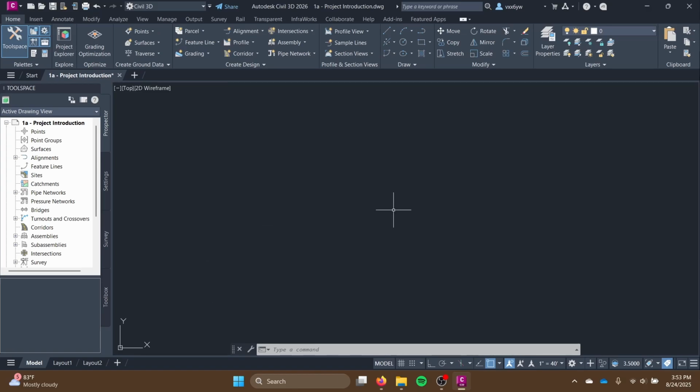The last thing to go over here, and sorry this is very long, is the command prompt right here. Civil 3D natively accepts all typing as a command. So if I just start typing anything, you'll see it'll pull up a little command prompt, and that's the same thing as typing here. So for example, if I want to make a line, I can just type in line, and then all of a sudden I can make a line. So don't try to use your keyboard to navigate. It won't really work. And we'll go over further navigation tools in a couple videos from now.